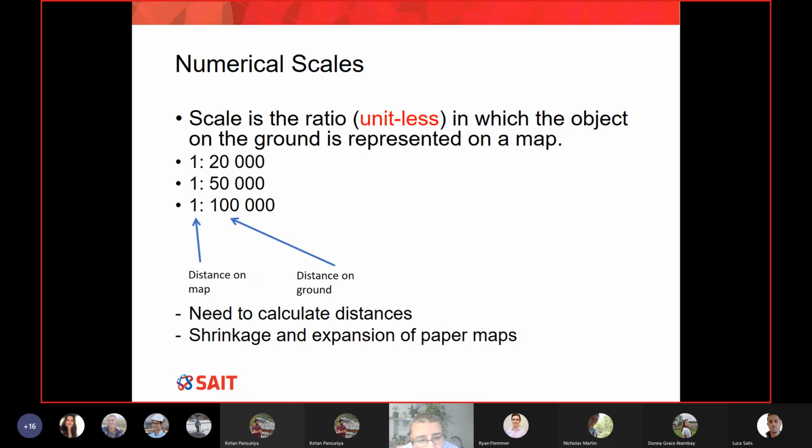Yes. Are you sure? For example, on an AutoCAD file, should I scale things down or up, or just draw 1:1? 1:1. So yes, that's true. On CAD, if I measure 3, it's 3 meters. If I measure 5, it's 5 meters. So in CAD itself, it has no scale because it's 1:1. It's exactly like the reality.